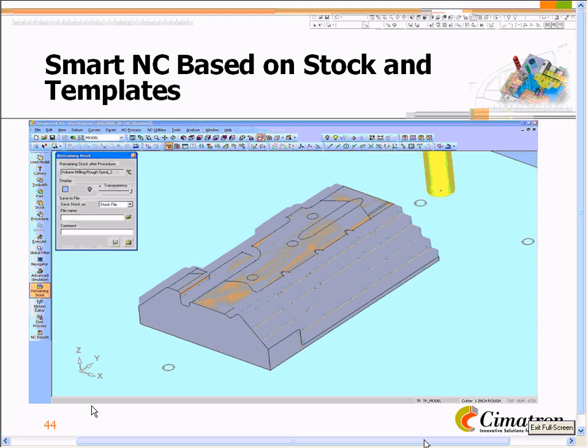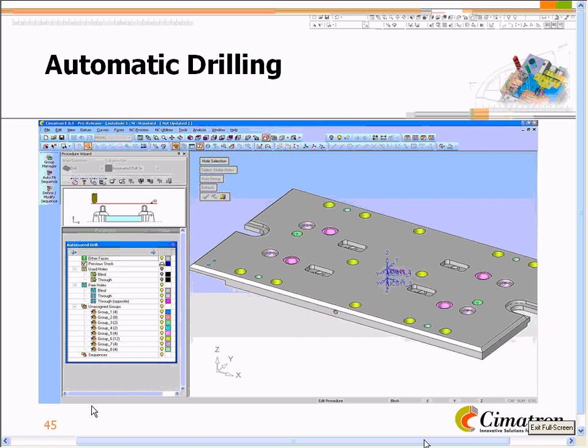But when we're talking about the concurrent engineering process, it's also very valuable for me to take my engineering change file and look at the remaining material that's sitting on the machine. Now I know if I need to go get another block. Now I know if I can continue with the steel that's already there. It's an important part of the decision that gets ignored because no one knows. You just try it, you drop the cavity, and you put a shim behind it, trying to recover that particular chunk of material.